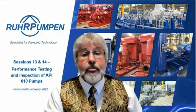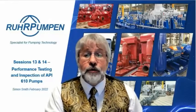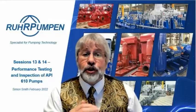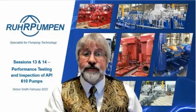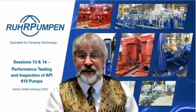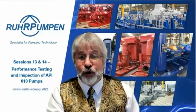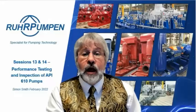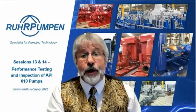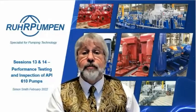Number two, most motors come with an abbreviated test. They don't come with a full performance test of the motor, so you don't know accurately its efficiency. And you need that to determine the efficiency of the pump. It's derived backwards from the overall power. So, that's why we tend to use calibrated shop motors rather than the job motor.